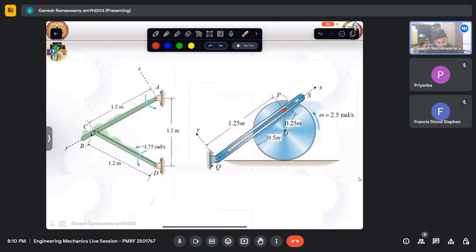Now we will look at the same point from a rotating frame. Regardless of which frame you look from, velocity has to be objective. Velocity has to be the same. By virtue of exploiting that condition, we try to relate that velocity to the angular motion of this slot, thereby calculating the slot's angular velocity, angular acceleration, and so on.